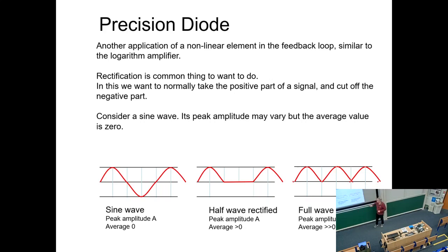And we can do something called full wave rectification, where we take the bottom half of our sine wave and flip it up. So now we've got that, and it's more sensitive to sort of demodulation and stuff. And we can take an average of that, and you can get this DC level go up and down as we change the amplitude of that. This is really good for communications for amplitude demodulation.